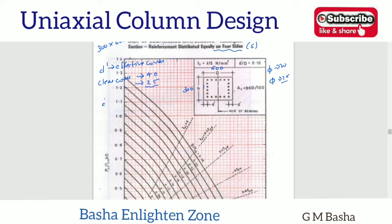Then what is your effective cover? 40 plus 25 by 2. If you take that, 12.5 plus 40 means 52.5. For example, if I am assuming a 25 dia bar for our case, it will be okay. Maybe there is a chance of assuming 32 dia bars also. In that condition we can't say exactly. Therefore, I round off this value to a nearby value which is 60 mm. So I am selecting 60 mm.